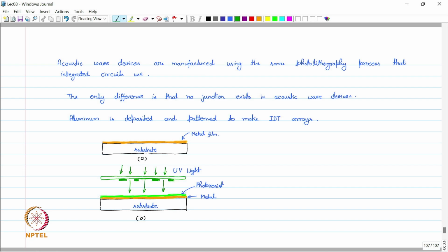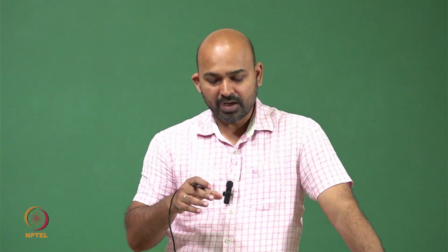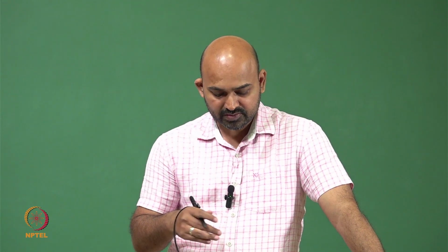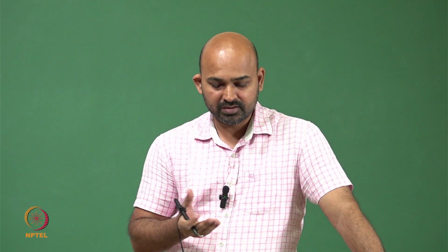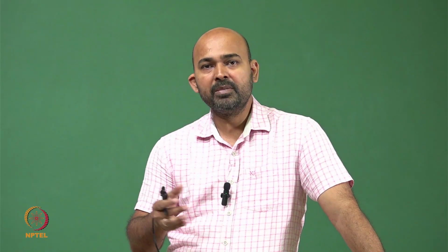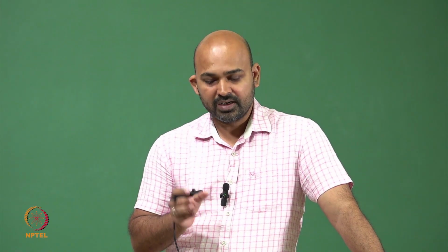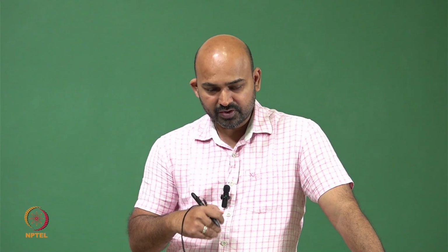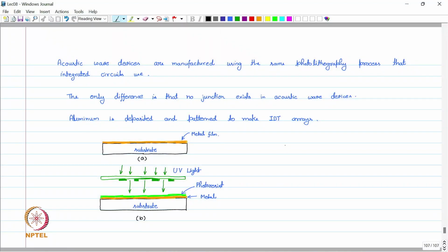Accordingly, the pattern will come on the photoresist and the metal. So when we use this mask, we are transferring the pattern on the mask to the photoresist, and the photoresist will harden where the pattern is formed. Then we use chemicals to remove this photoresist, and the same pattern will be transferred to the metal. So in step C, we have this pattern transferred onto the photoresist.